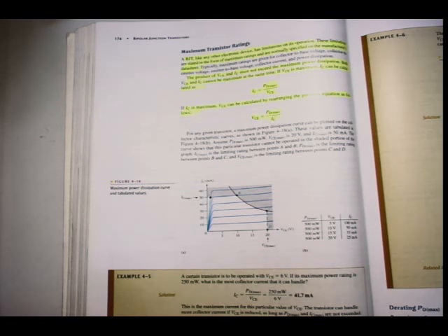If you recall the characteristic curve that I have of IC against VCE and the load line, as I move up and down on the load line, I can imagine if I move closer to 0, then VCE will be less, but IC will increase. And if I move down on the load line, you can see that my IC will become less, but VCE will increase. So they cannot be both high at the same time. That's all that they're saying here.